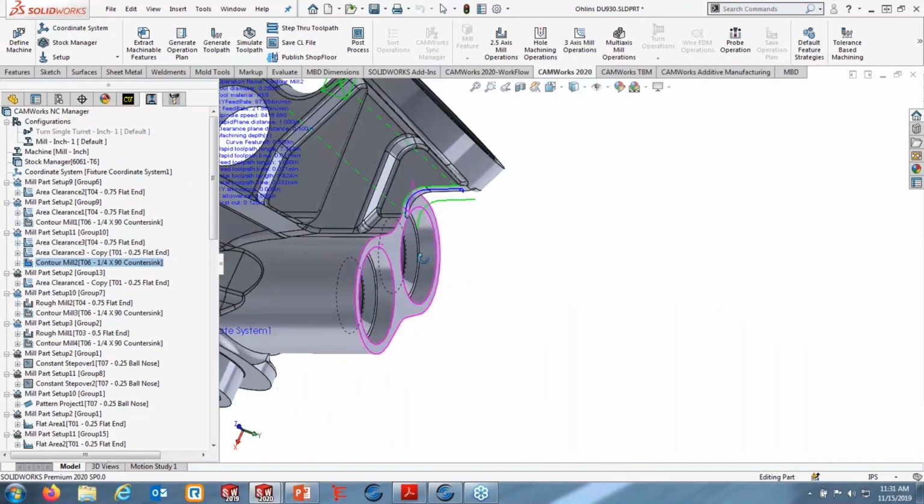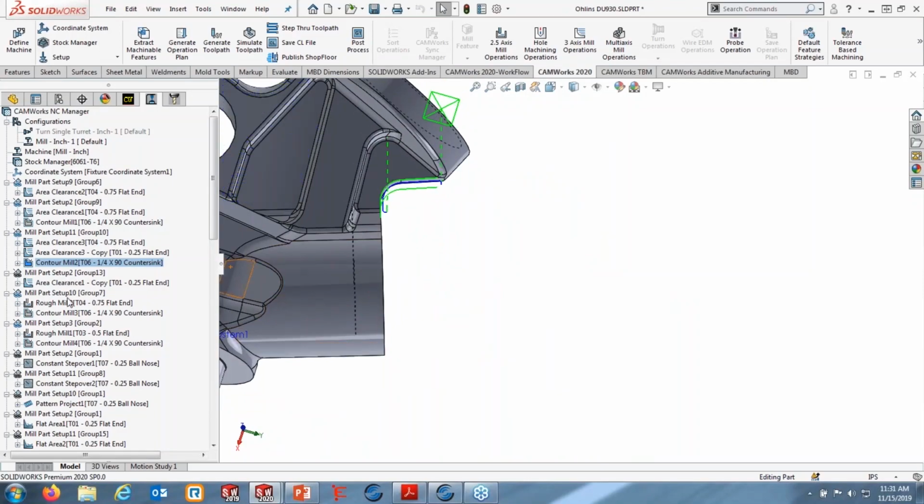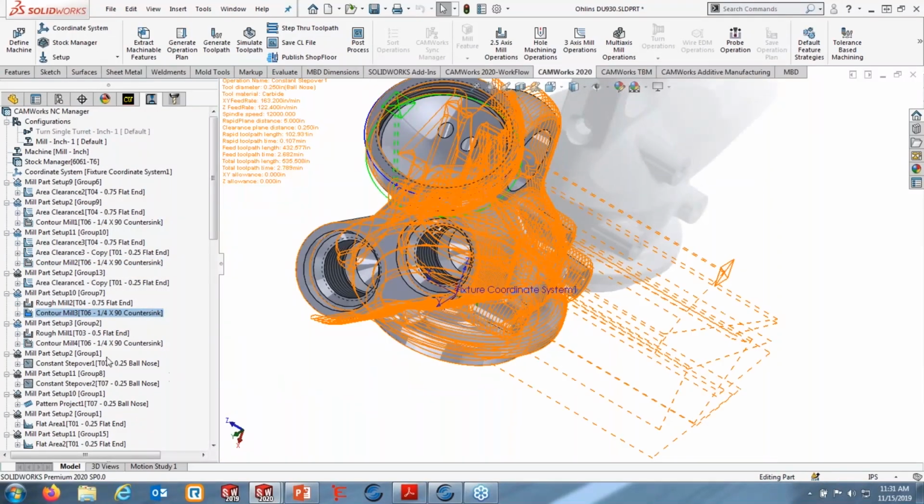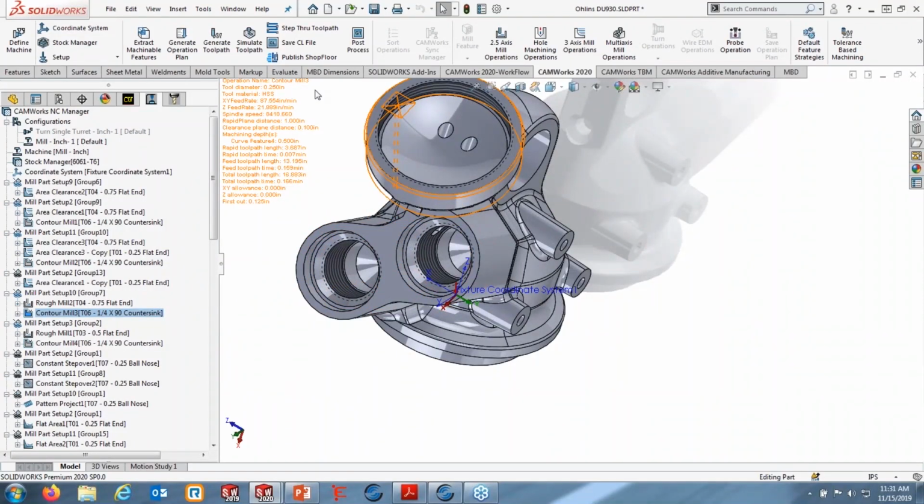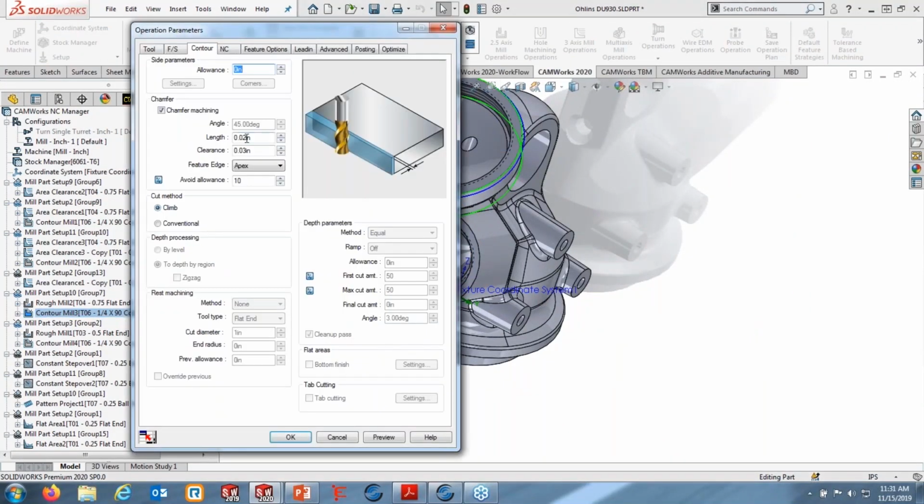So you'll see right there, you'll see right here. And you can control the depth of the chamfers and things like that. It's just using your strategies in your database, so you can control this and set, well, I deburr everything at 10 thou. Go in and change it, save it back to your database, and it'll do 10 thou next time.